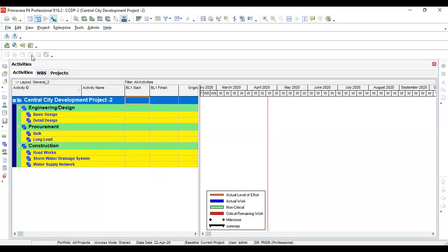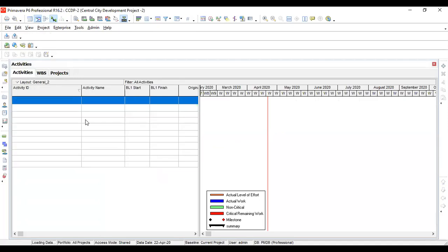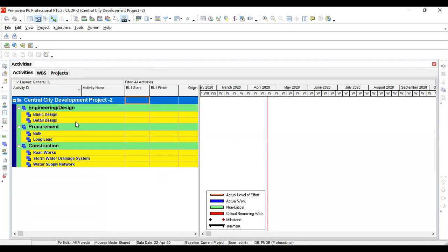Every time you develop something extra in your WBS, don't forget to click on refresh data, so if something is missing, Primavera can align it with your required sequence. Okay. So there are different levels we will talk about in tomorrow's lecture.